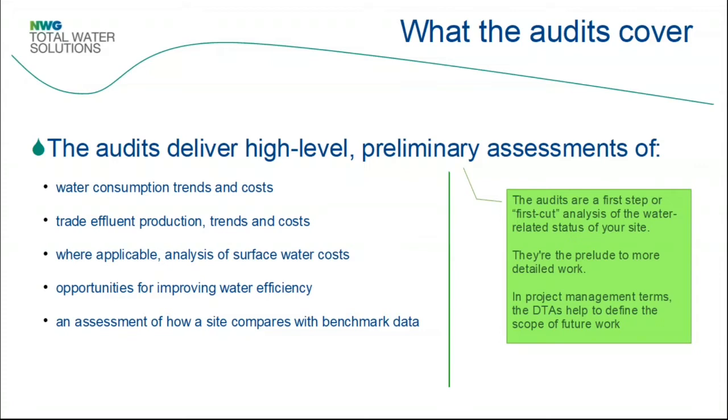The consent is a physical document that gives you permission to discharge that material to the sewer. If you discharge it to the sewer without having that consent, that is illegal. You are not allowed to discharge trade effluent to a public sewer unless you've actually got permission to do so. And not only do you need that permission, there is also a charging mechanism which is used to work out how much you pay to have your trade effluent discharged to a sewer. And quite often there can be savings to be made by changing the way effluent is managed and treated on a site, or perhaps asking for variations in your consent, which could perhaps work in your favour.